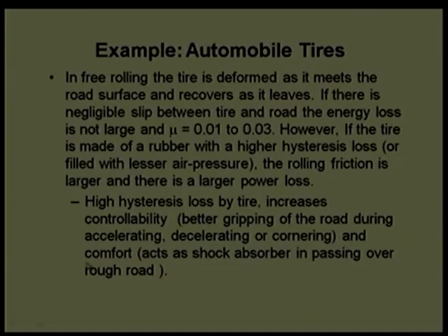In addition to that, this deformation provides some sort of comfort. It acts like a spring action, or maybe part of a shock absorber. It does not transmit all road unevenness to the passengers. So, from the comfort point of view, some elastic deformation needs to be there. The rubber material should not be very rigid or solid, otherwise the whole vibration of the road, whatever the road condition, will directly get transmitted to the passenger sitting inside, and it will not be a very good option.